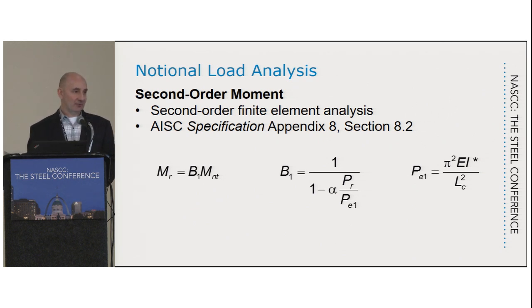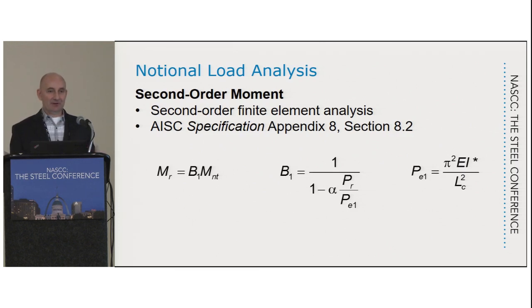Okay, this is the hand calculation method, and this is the method that I've used before. But you know, being that I'm not that computer savvy, I kind of do the hand calculation method unless something really comes along to make me want to change it. And as it turns out, after I started looking at this, using the second order finite element analysis is really going to give you a little bit more accurate answers because you don't have to do an estimate on EI on the properties for that. But it's very easy to do.